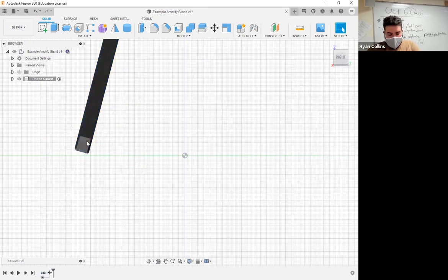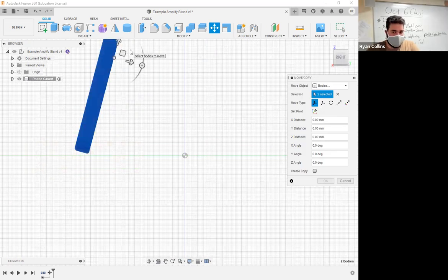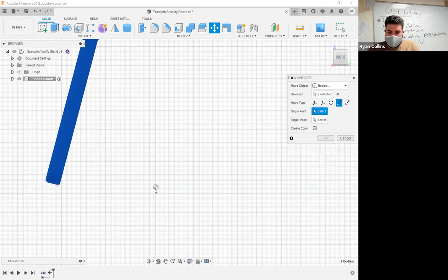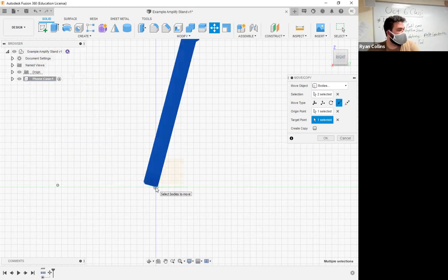Okay. Click OK. Great. Now I'm going to move this back to a better position. Now the problem here is it's orienting to that angle. So I have to do that again. Select a point down at the bottom, something to that effect. Yeah, that ought to work. Or what I can do is select point to point. Click there. My origin is not active, so reactivate the origin. And I can actually use that as a selected point. Snaps over to there. So it's just a couple of easy ways to move some stuff around and orient things. Okay, cool. That's all I wanted. All right, great.